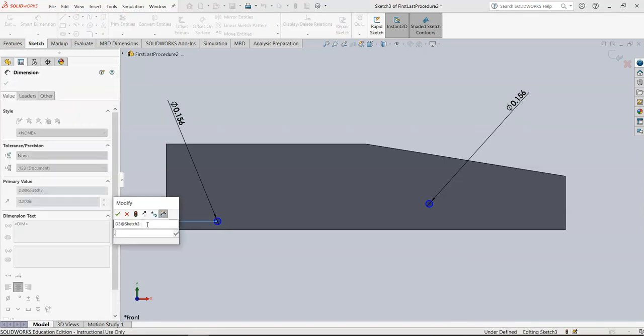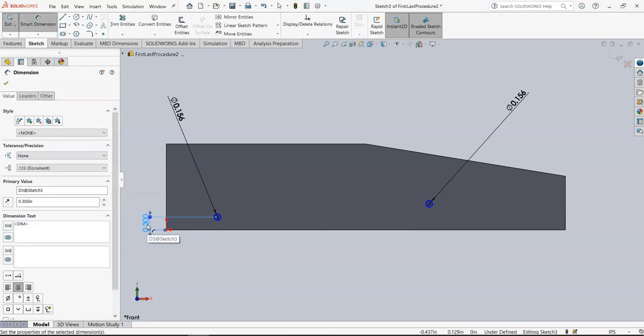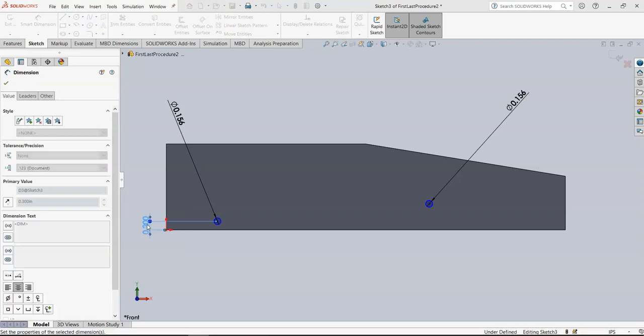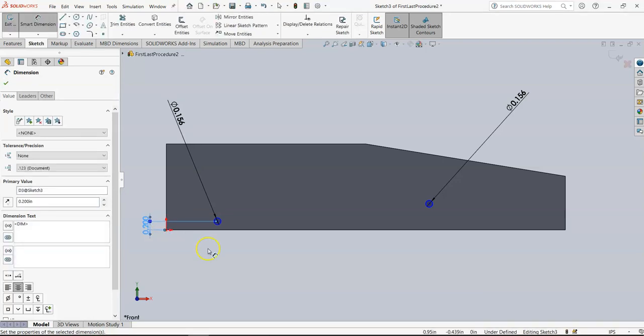So there's nothing stopping you from having 0.3. You can do 0.4. You could really do whatever you want. There's a benefit and a positive and a negative to both of these. This is essentially setting the ride height of your car. So at 0.2 inches, you're going to have the highest ride height, which is going to give you a little bit more clearance below the car. There are going to be two eyelet screws below the car that we run a piece of fishing line through so that the car doesn't careen off of the track. So we're essentially playing with ride height right here. If you make it 0.4, you'll make your ride height the lowest. Has a benefit and it has a negative to it.